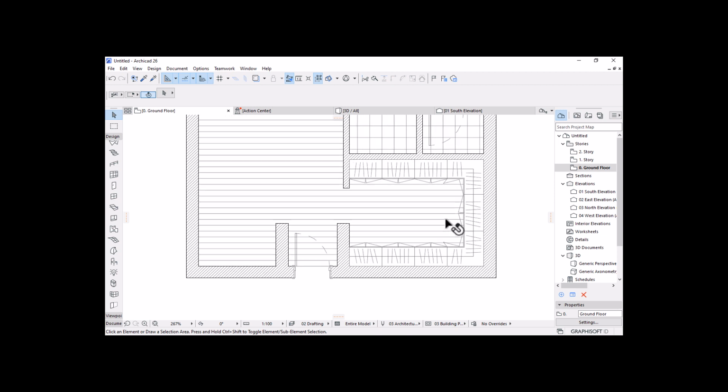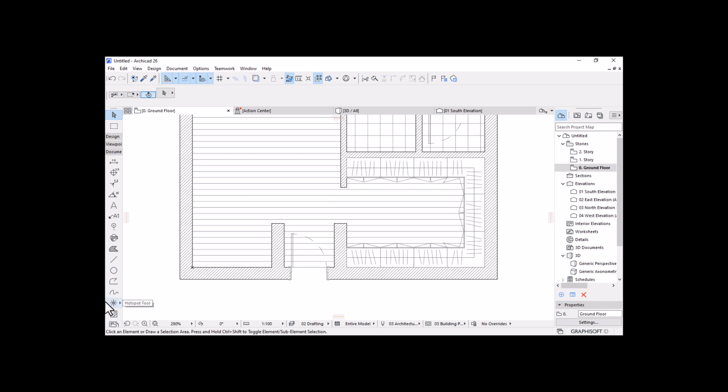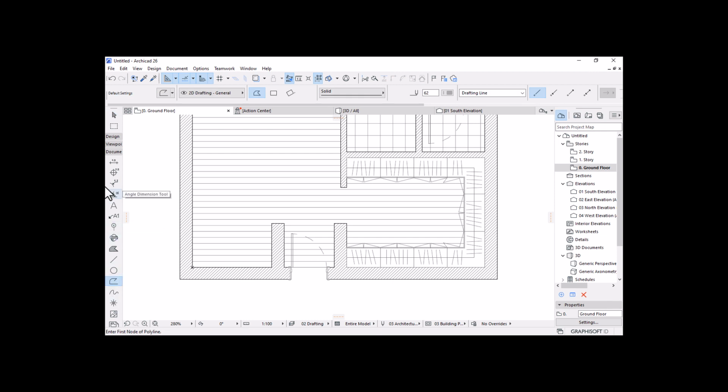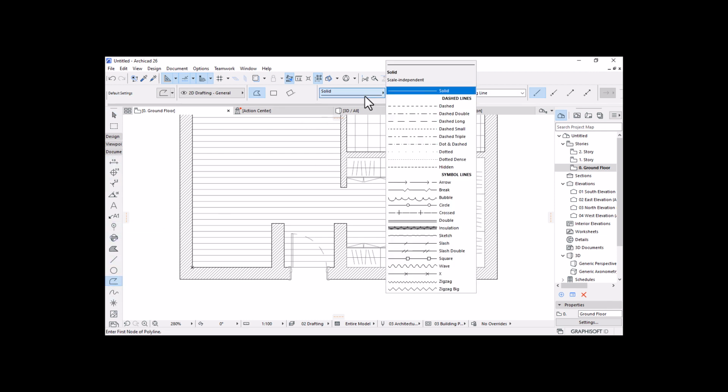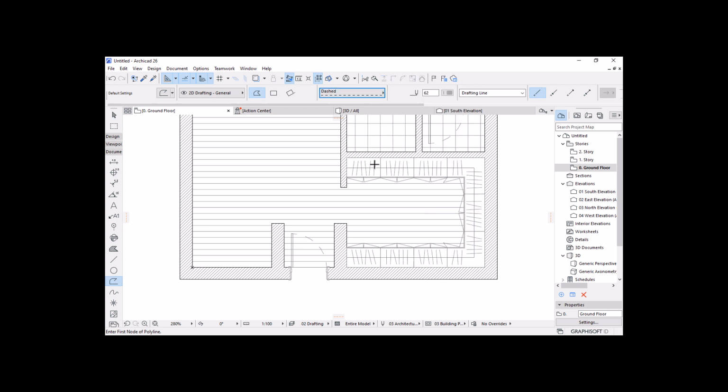Right, so I could come here and then use, and I put an extra detail. I'll select under document, I'll select a polyline tool and then change the line type to be a dashed line type, and then I'll come draw it as a box. Let's change the geometry method to a rectangle. Let's just draw this. This is going to be just an indicative line, and then select this line, offset it